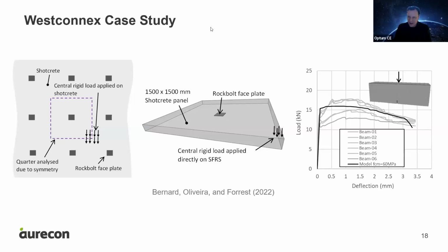Great. We have another couple of questions, David. Can this be used for cut and cover tunnels? So more of a rectangular shape than a circular shape? Obviously you can always use fibers to enhance something. Most of the codes we use for pure fiber reinforced are European codes. Here we use the fib model code. The only code we have in Australia is fiber together with conventional reinforcement. So obviously the Australian code is already thinking of those cases.